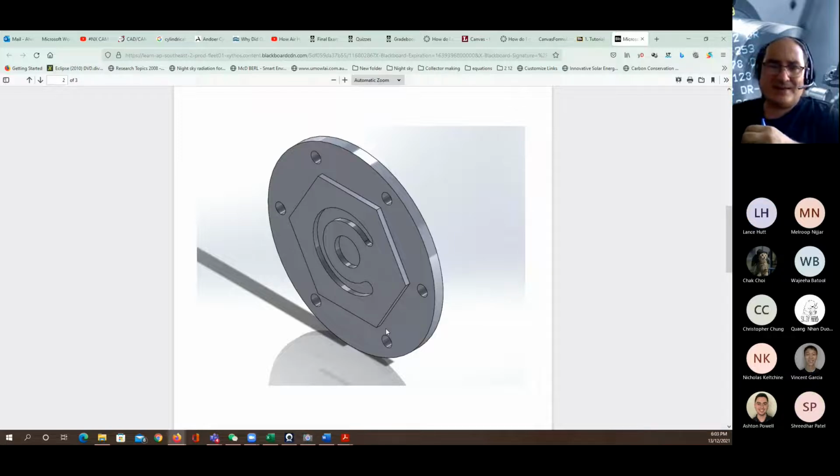Because sometimes the work part itself, when we say the work part, that means the piece we're going to start working on, they're not going to have the same dimensions. And that's why we always prefer to take it to the corner. So when we remove the material, we're not going to hit the vise.